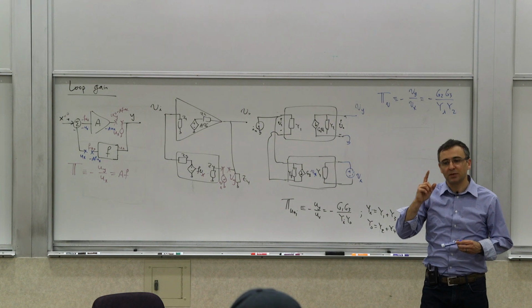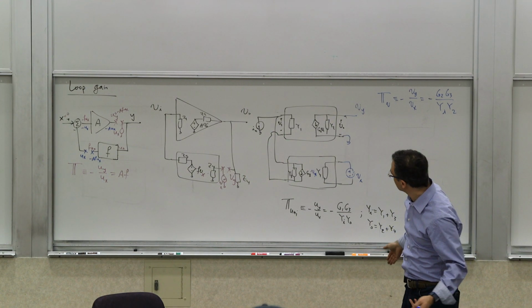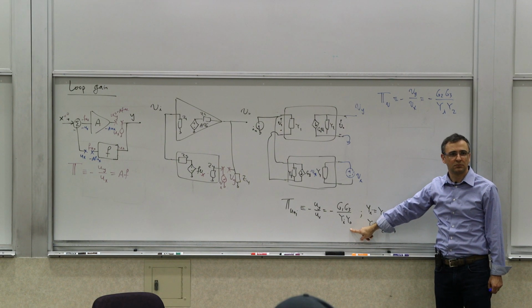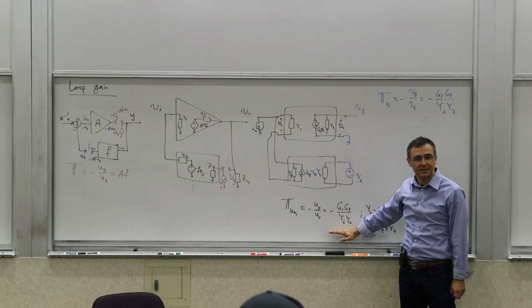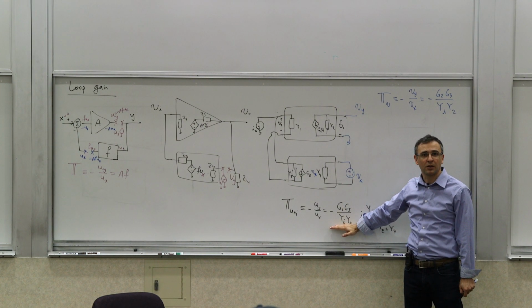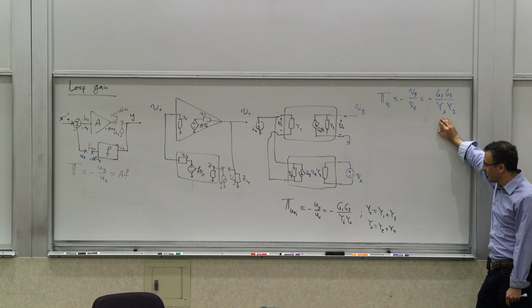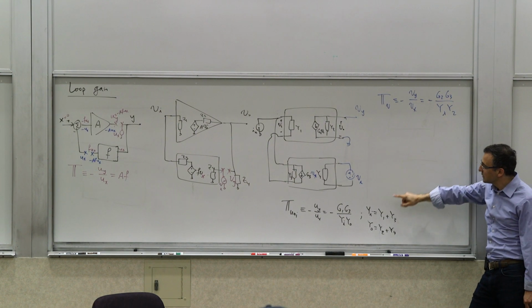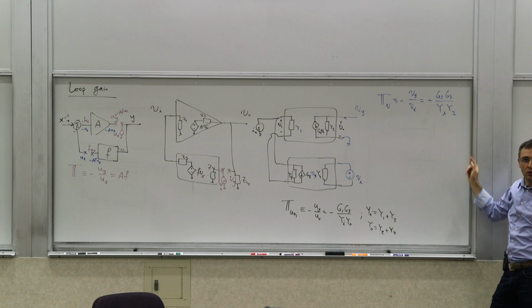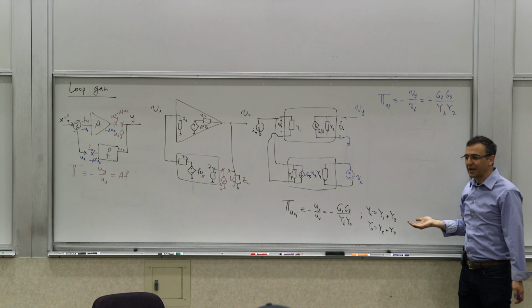You could also do the opposite. So you can say, but clearly this is not the same as this quantity, right? You said this is the loop gain. This is the unilateral loop gain. If we took the loading into account, this is the correct one. So you can clearly see that this is not the correct answer, because this is YO and this is Y2. So you can see that if you don't take the loading into account, it's not accurate.